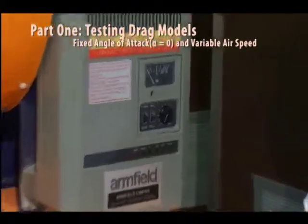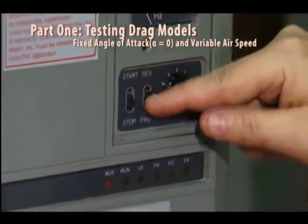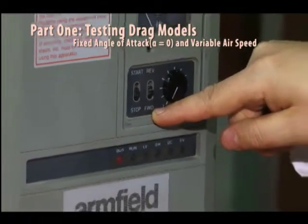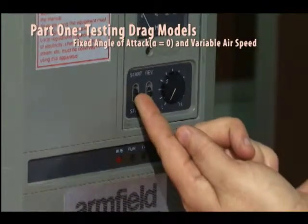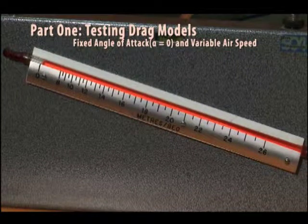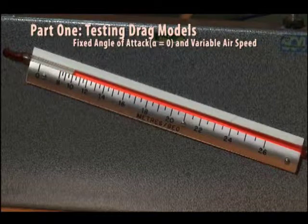Make sure that the motor is set to forward direction before turning on the motor. Turn the AC motor on and slowly increase the motor speed and stop when the manometer indicates the required air speed.